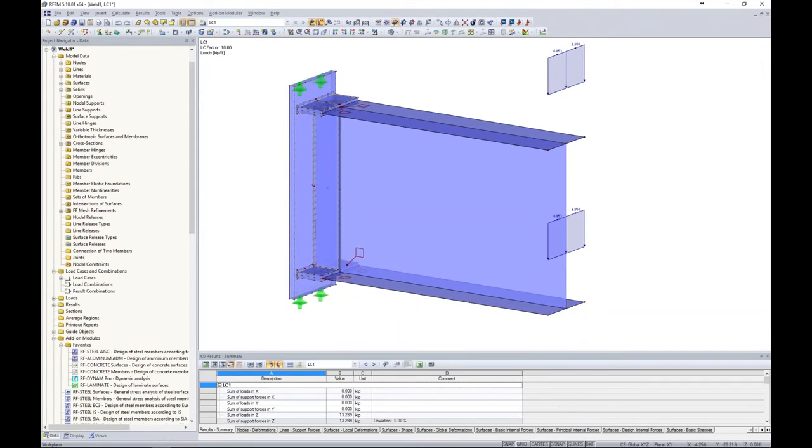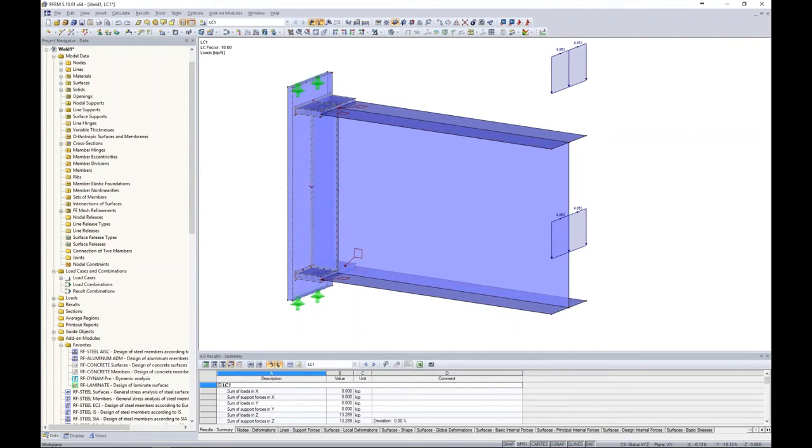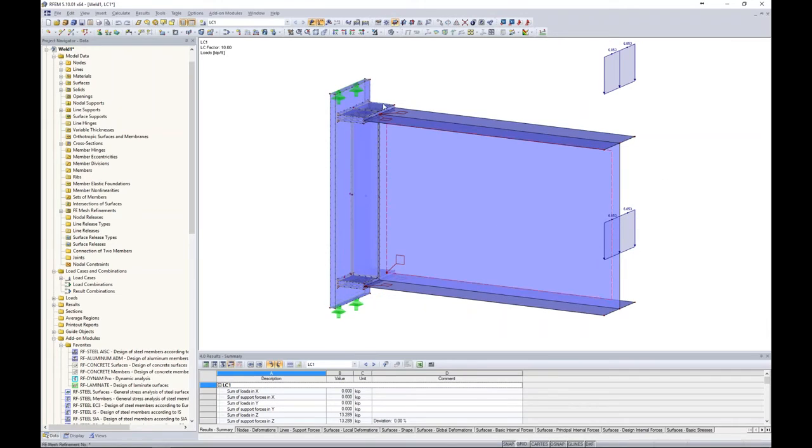This would be completely independent of contact solids. So I didn't utilize any contact solids within this model, but let me explain what's going on. So of course, we have our W shape consisting of our typical surface elements that we've been through many times now. But you'll notice up here is my plate that my beam member is being framed into.